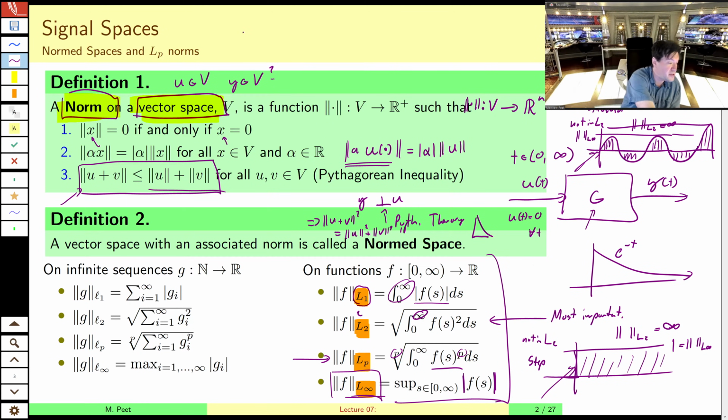And that makes sense. An impulse is usually well-defined. If you give an impulse to a system and the output you get is a sinusoid, basically you're taking a finite energy kick to the system and producing an output which has infinite energy that goes on forever. We don't really believe in perpetual motion machines, so we don't consider this to be a well-posed system.